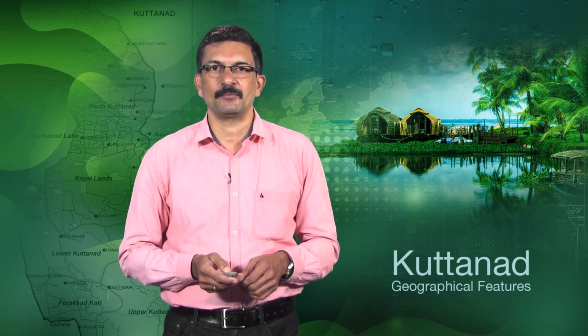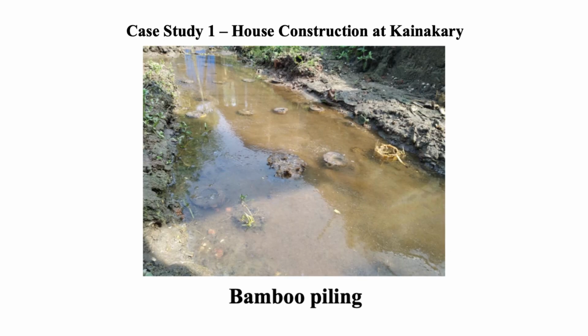The width of the foundation was also suggested so that the bearing capacity of the soil is sufficient enough to take care of the load from the superstructure. So, it was a wider foundation, and bamboo piling was given as well. The advantage of this bamboo piling is that the soil in between the bamboo piles will be collected as a single unit, and the soil will act along with the foundation for load bearing. So, that is an added advantage.